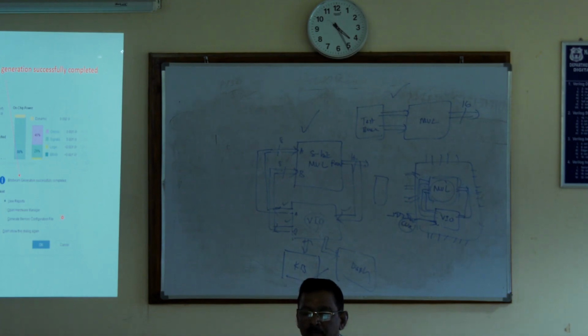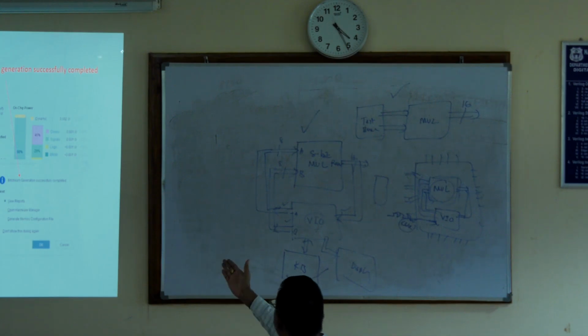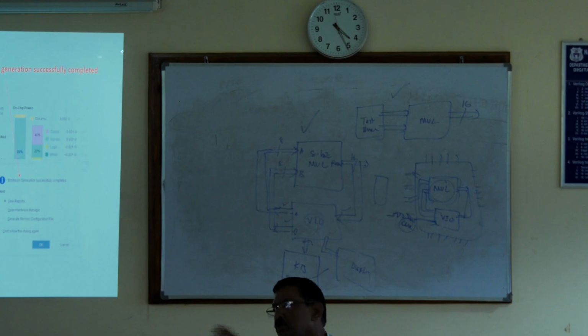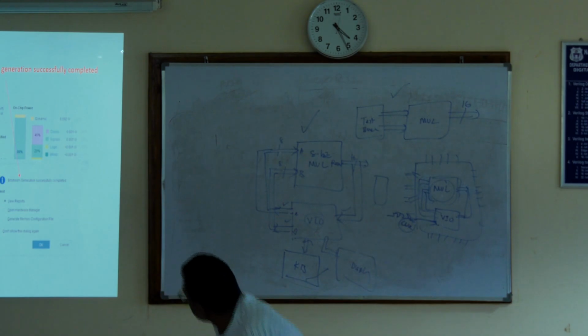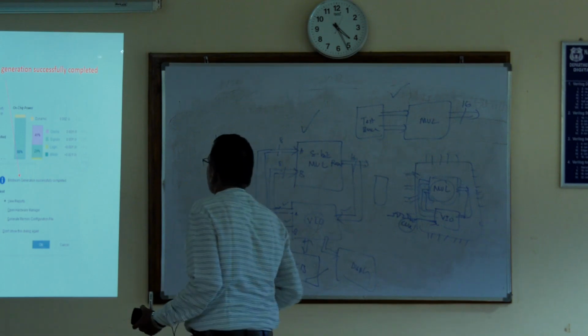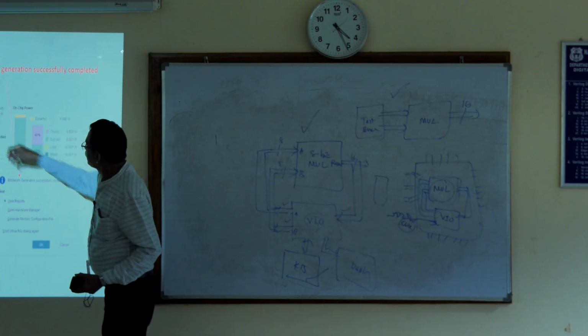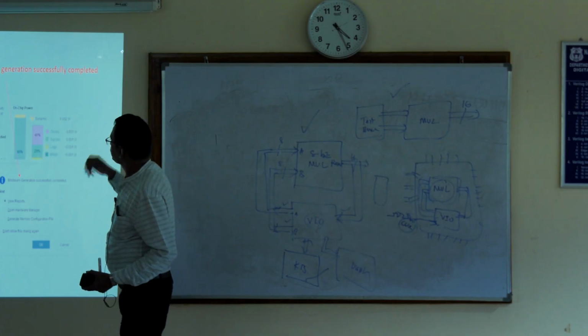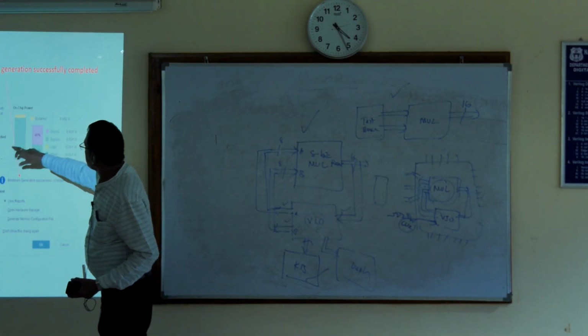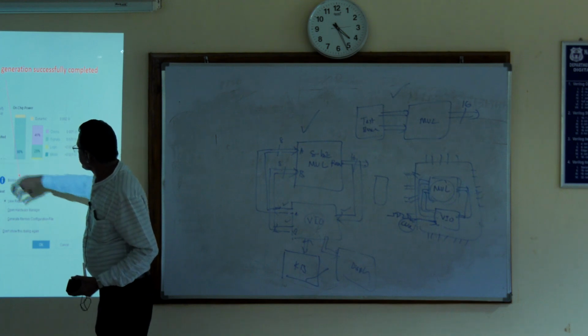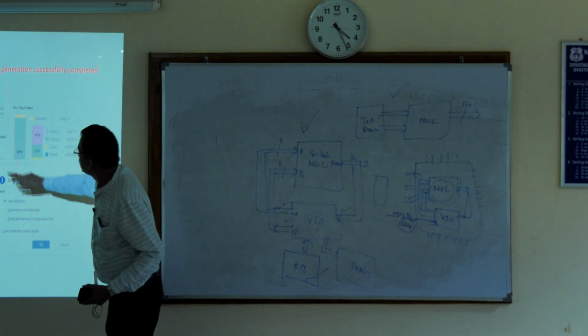Okay. So after the bit stream, we can also see the reports. All these reports, after synthesis only it is going to come. These reports indicate how much power this logic block is consuming, total power of 0.0185. Then temperature, thermal margin.